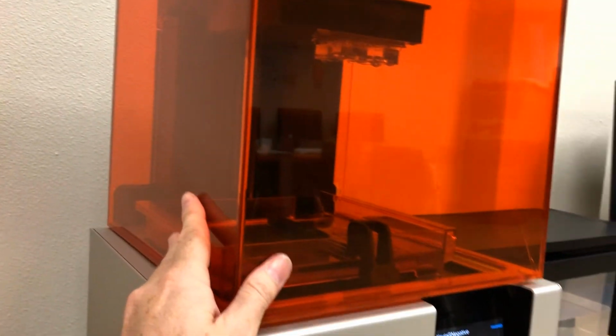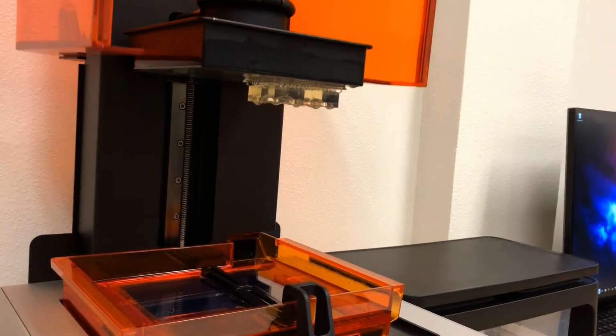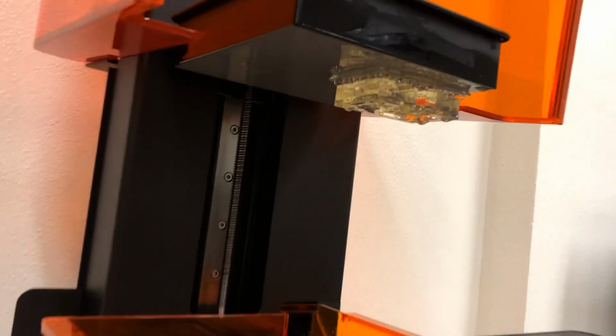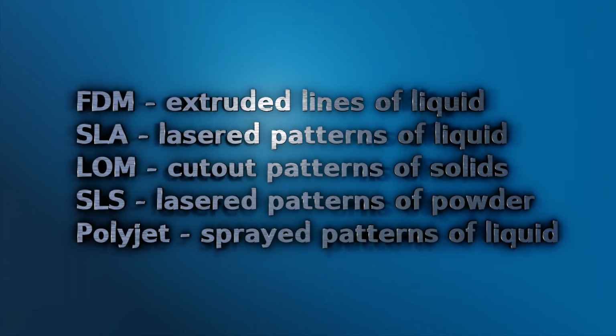Stereolithography, or SLA printing, solidifies layers of patterns from tanks of photosensitive liquid resin using lasers or illuminated images. The SLA process is fairly inexpensive and slow, and the resulting prints are typically highly detailed but fragile. Due to the positioning of SLA illuminator arrays along with clear-bottomed trays, this approach creates objects in an upside-down fashion as they emerge from liquid resin tanks.